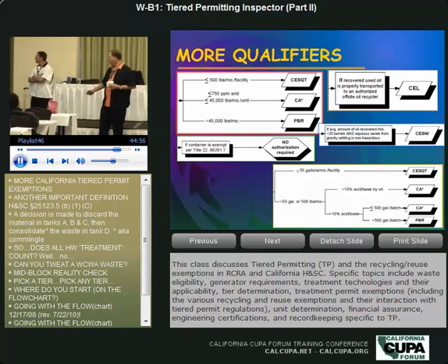Here again, over 55 gallons per month or per facility, less than 10% acid by weight. And now it comes into batch treatment. Let's say somebody has, and I think this is the acid-base neutralization one, an acid or a base. They're treating 100 gallons per month. Okay, so they're not up here, so now they're down here. Let's figure out what the concentration is. It's 10% or more acid or base. All right, it's 11% acid or base. So now you know you're down here.